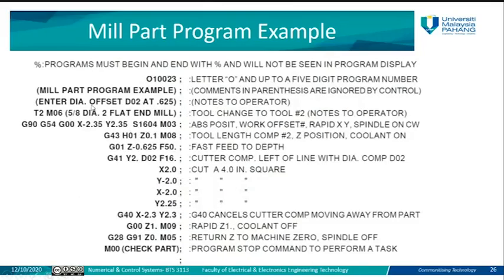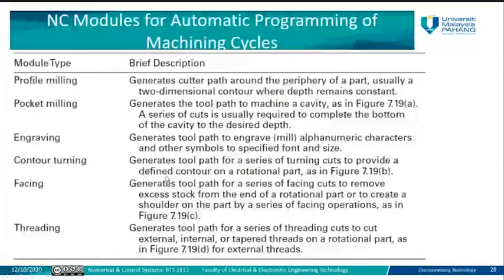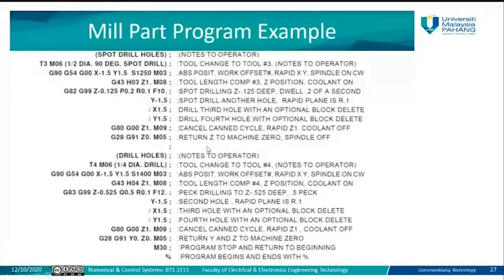First, you define the first tool, and all in between what you need to do. The information that we see here, X, Y, Z, F, will be given either through engineering drawings or in a table. So the task will be just to write such coding. We are going to see a complete example of this. Instead of developing a complete program from scratch, there are some macros, like we mentioned before, the canned cycle and the fixed cycle.